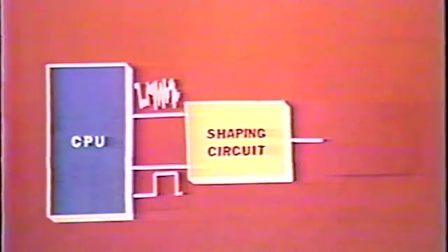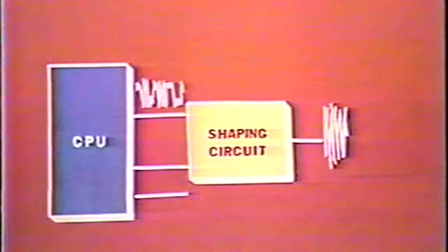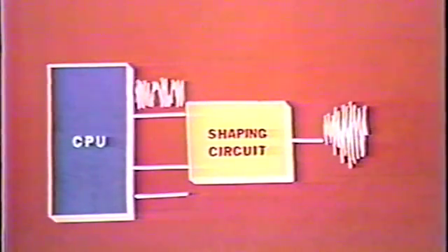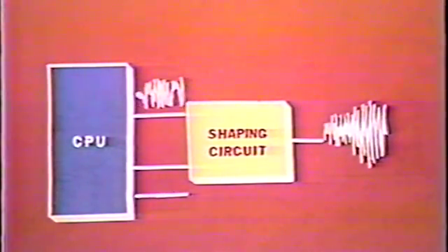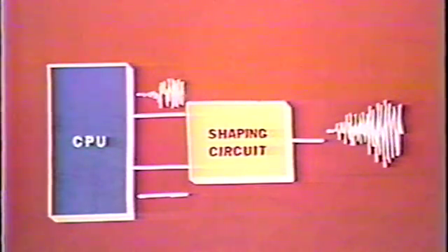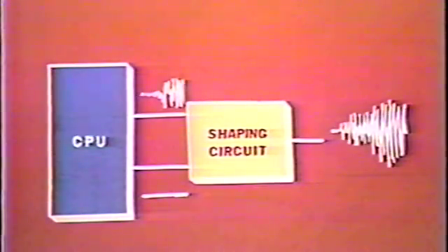The cymbal and hi-hat sounds are created with white noise. White noise is noise that contains components of all frequencies and sounds like a hiss when output by the amp. The cymbal and hi-hat sounds are created by shaping the white noise in the cymbal and hi-hat circuit. The accompaniment LSI outputs white noise and trigger pulses. The trigger pulse is changed to a tapered waveform in the shaping circuit and mixed with white noise to create the cymbal and hi-hat sounds.